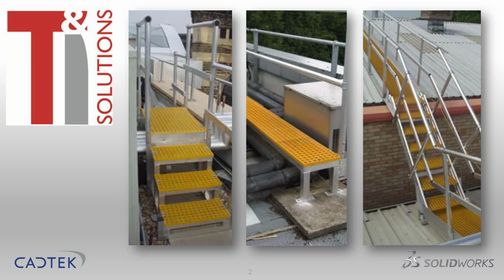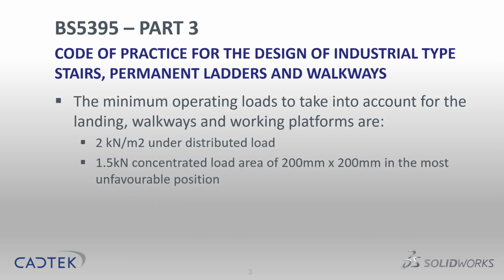So just what tests do we need to apply to comply with the BS 5395 Part 3 standards? Basically there's two that apply just to the platform. The first is a distributed load of 2000 newtons per metre squared over the gangway, and then we have a concentrated load of 1500 newtons in an area that's only 200 millimetres squared, and we have to choose what we think is the weakest area of our design.